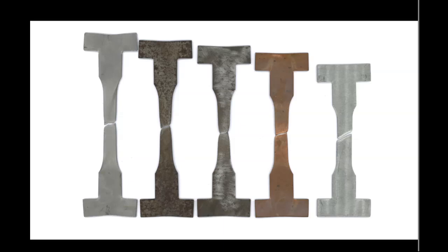Okay. And again, when you ask to explain any discrepancies in terms of deformation behavior and necking, if there is pronounced necking, the materials with significant percentage elongation and significant percentage of RA will always have defined necks, will always have significant visually visible thinning in the fracture area.